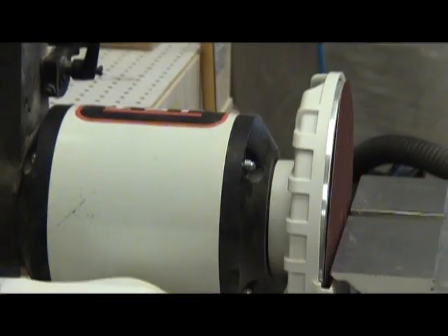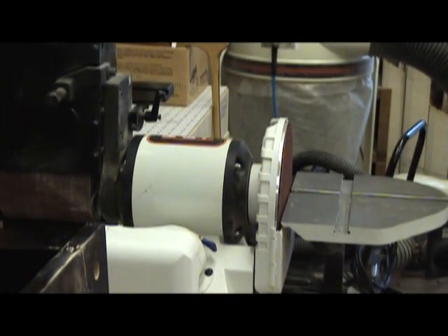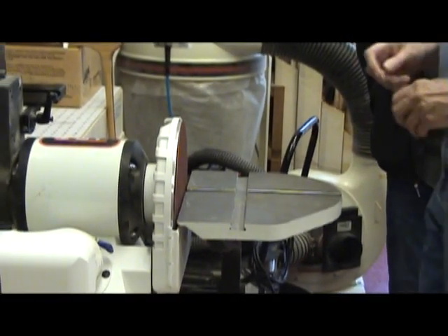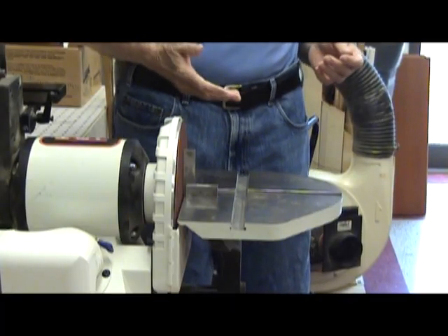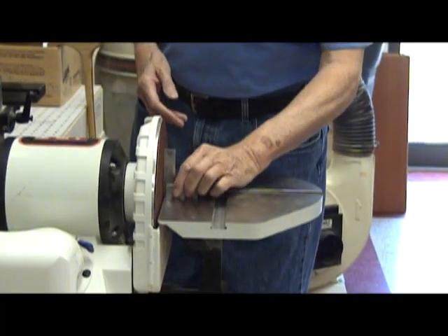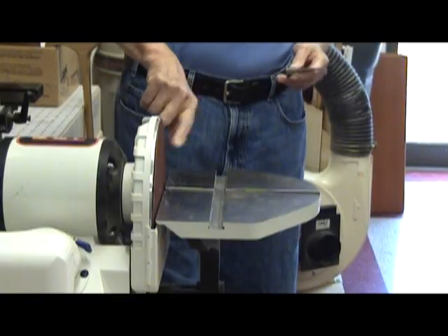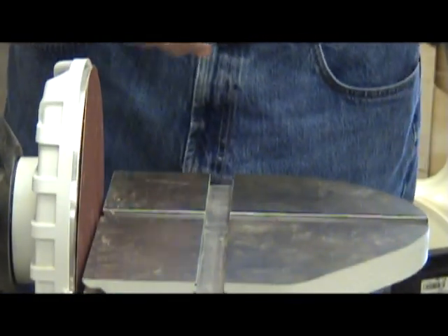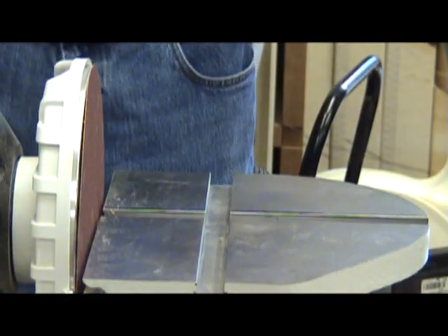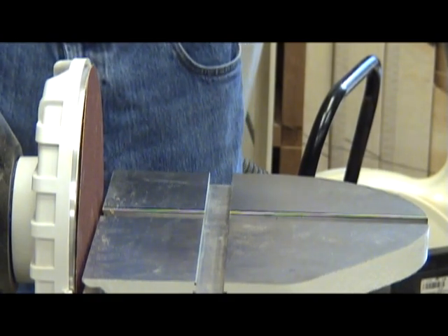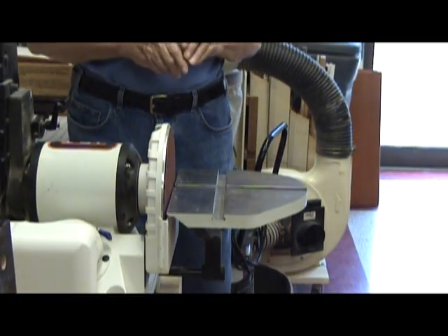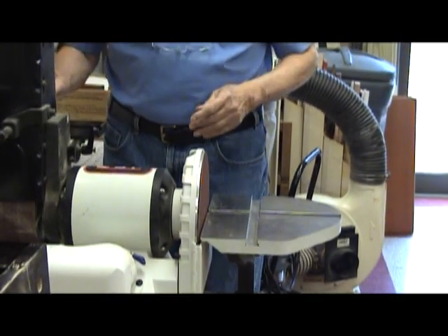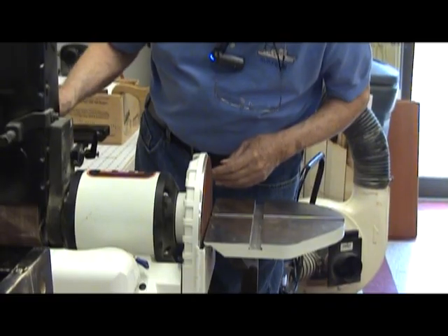One of the issues we have with all of our tools is we never know whether the tool itself is calibrated. So I'd recommend that you bring a square over. It turns out that this one has always been right at 90 degrees, but quite often people will put some weight on this particular face and throw it out of square. So I would recommend that you always check.